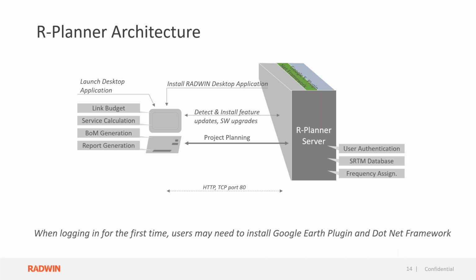As I showed you at the very beginning of this course, I always want you to remember that the App Planner is based first on the RADWIN product. It has all the capabilities and all the technical specifications of each unit or each device or each ODU: the C/I, the sensitivity, the modulation, the TX power, the antenna gain. And remember, when we are doing the planning, it's based on link budget calculation, the same as I showed you at the very start.